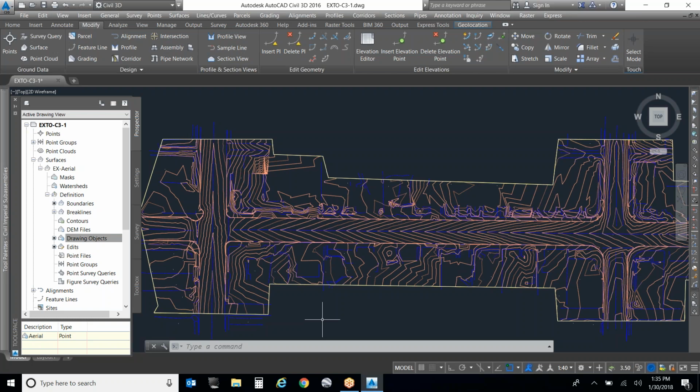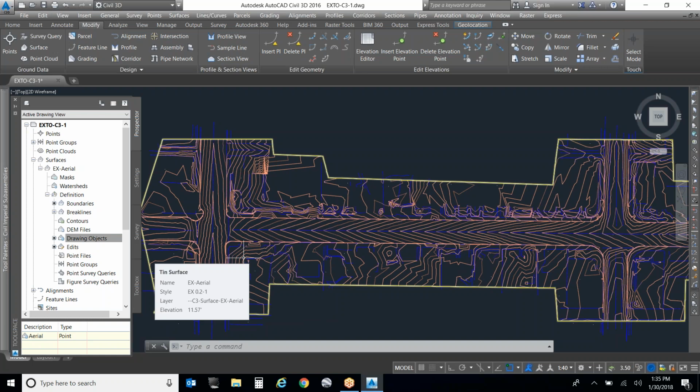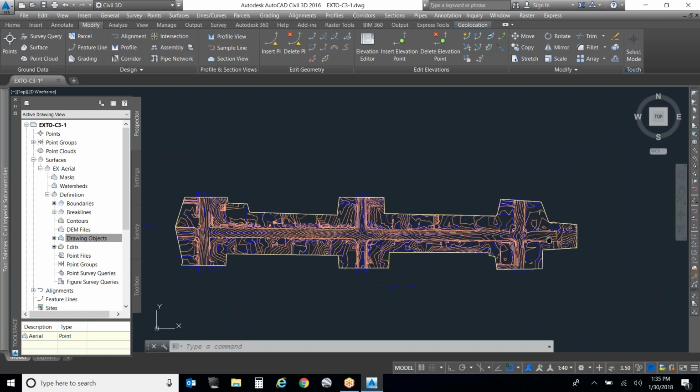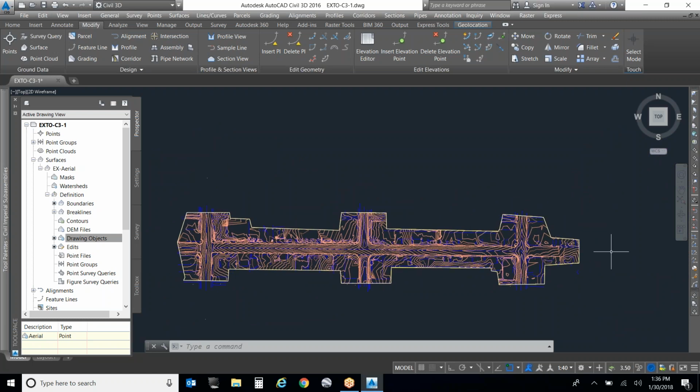Again, it's one of those things where it's engineering judgment, and each project manager is going to look at that a little differently. So you need to have the conversation. And since you brought it up, on pothole data, you should actually be projecting those points to your profile. Then you would visibly see what kind of differences you're talking about between your pothole elevation and your aerial profile, or your profile derived from your aerial surface.